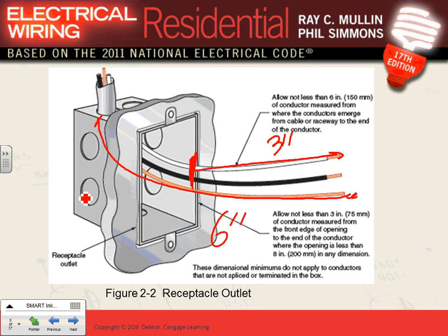If the code allows 6 inches, it's really a good idea, guys, to go a little bit higher than that. Like you said, 8 inches, 10 inches is not bad. Just to allow for the future, because guess what? You put your receptacle here, you have a short, you burn a little bit of the insulation, you cut it, you push it. Remember, you are designing a system for 50 years. Keep in mind the poor people who are going to maintain this system for 50 years.